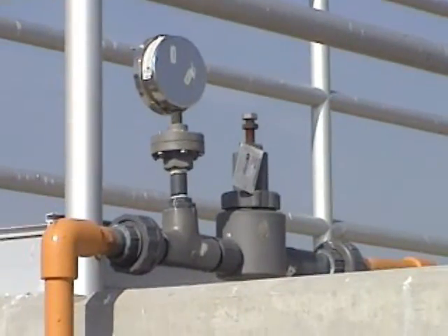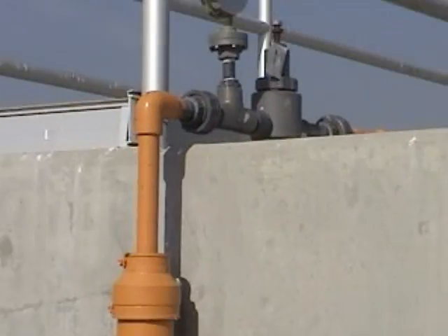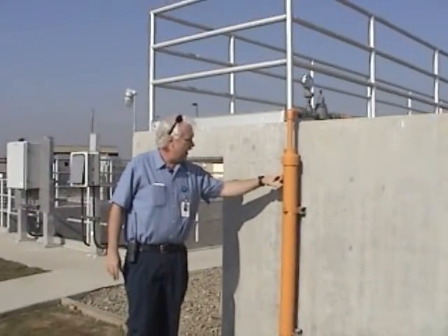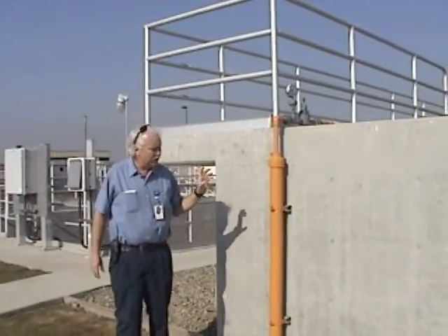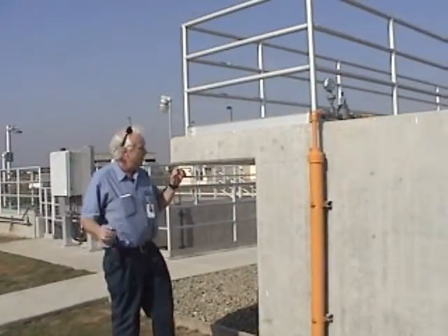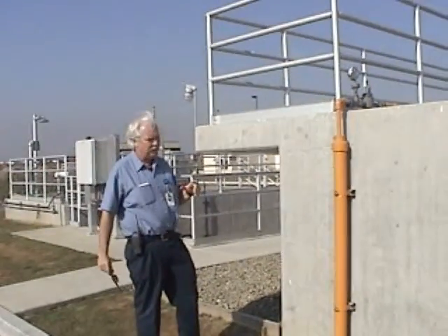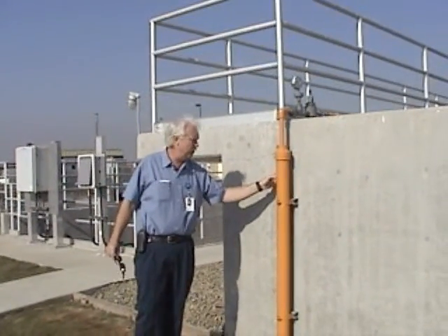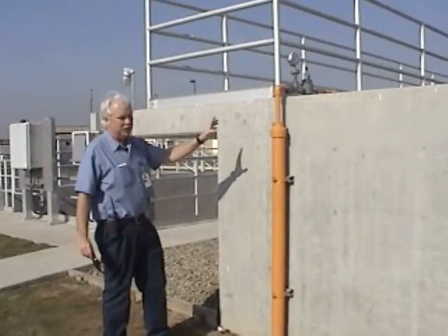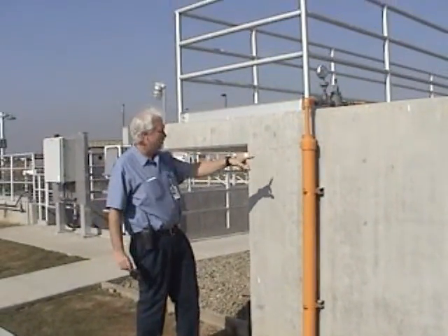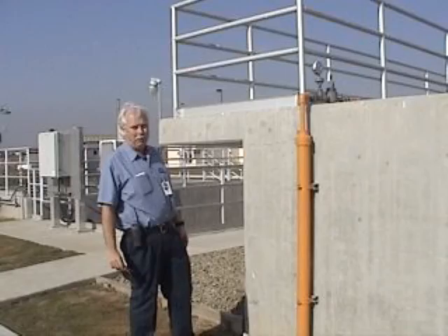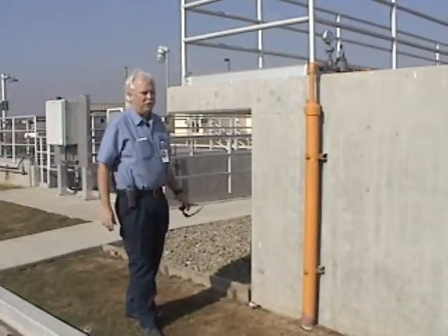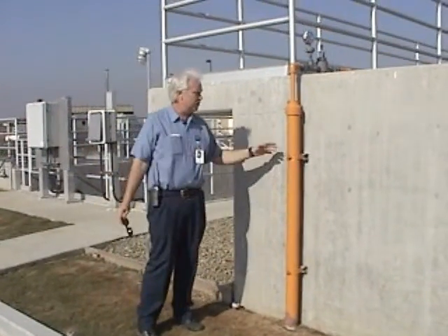The thing you'd have to be aware of, though, if you're dechlorinating the plant's effluent from here using pump number 2, is that you're working with very little safety. There's no other way to dechlorinate the effluent after this. If this pump were to fail, or it's not set properly, you're not going to dechlorinate the effluent and you're going to discharge a chlorinated effluent. So if they have to service that dechlorination point down there, it's really, really important to keep a very, very close eye on this.